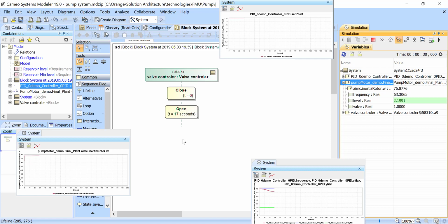So we can do import from different tools. Dymola is the primary tool for FMU export, and we can do different FMUs with the development of new components. We can compare them, do trade-offs from the system architecture perspective, gain traceability to requirements, and then really automate the requirements verification with the updated system design.